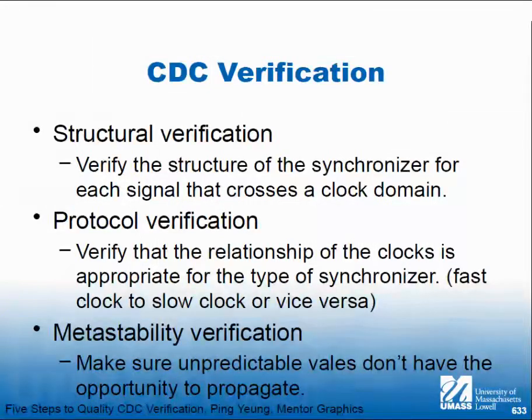I don't know, but here's the worst problem. Radiation-hardened systems have to be designed expecting that there's a reasonably good probability that a flip-flop is just going to change state. So you have to put in extra logic that will handle that. I'll give you an example in a minute, but what happens is you do that in your code, but the synthesizer looks at it and says, oh, you don't need this. That's redundant. I'm going to take it out, and it optimizes it out. Then you think you designed it in, but you really didn't.